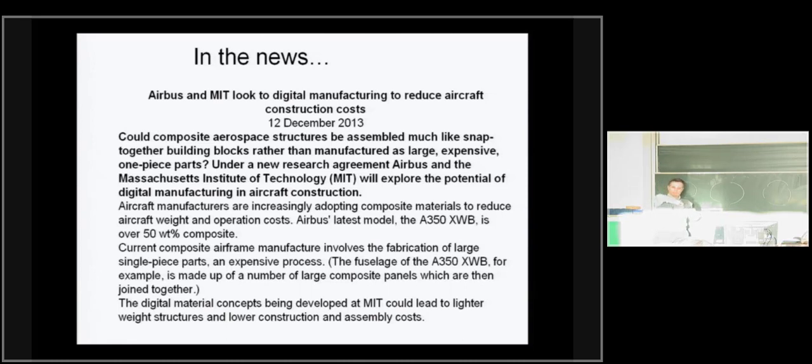Okay, but that's an afterthought. But it does help to have more lines or to move cracks around if they grow in the wrong way. But before that, suppose I made these and they are nominally identical. They come even from the same mold. Now, when I come to connect them, they will never match. If I match exactly at the top, usually there's going to be a gap one way or another at the bottom. You might say it's small, it might be only a few millimeters, but closing that gap means a few millimeters' worth of a bending moment you put in, and you don't want that on top of your other loads.